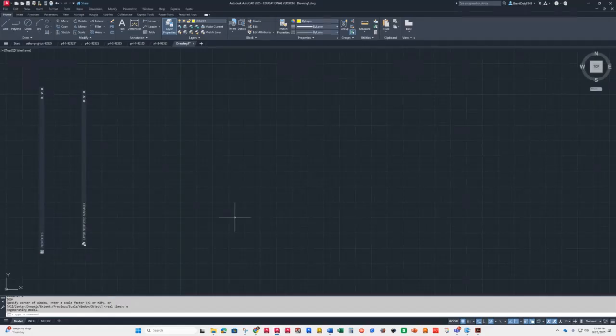So, how do we pick which is which? We pick the one that has the least amount of hidden lines. And in this case, the way this is oriented that we're shown, it would be the end closest to the cylinder. Okay, so that's how I'm going to approach drawing it up.